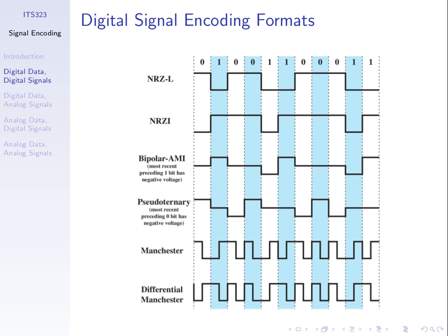But with, for example, non-return to zero, if we transmit a sequence of zeros, our signal is always at +1 volts. With a long sequence of zeros, the signal transmitted will be at the same level for all those bits. There's no opportunity for the receiver to synchronize its clock in that case. It doesn't know where one bit ends and the next bit starts.